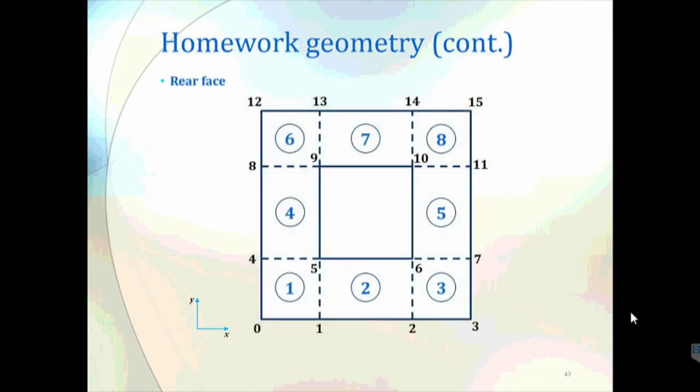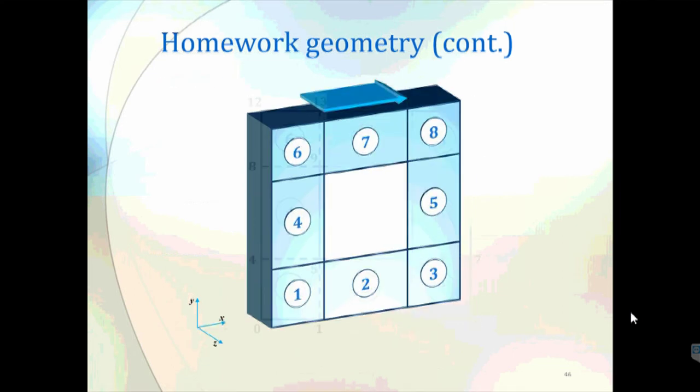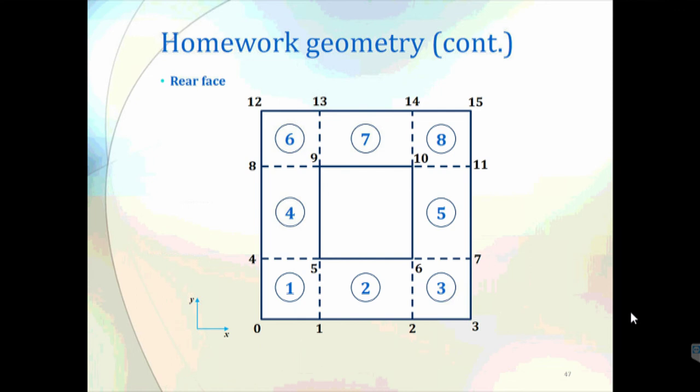So the next step, what's the next step? We have to describe the points and we have to describe the faces. Remember, I told you in the beginning of the lecture that OpenFOAM mesh generation is described in terms of points, faces, and blocks. So we have to describe the vertices of all the points. We have to describe the faces for each of the blocks. And then only can we move on to making the individual blocks. So after describing the points, the next step will be to make the faces, all of the faces.